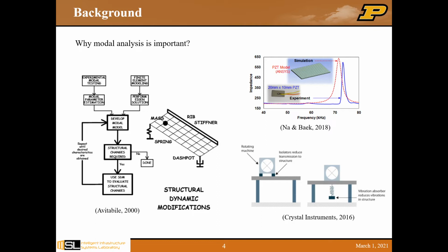Usually we will have finite element modeling, and we will also have the modal testing from the lab. And then once the model has been validated and verified, we can use that model to simulate and to evaluate any change that we made to the design, right? And without building a physical system with this change again.